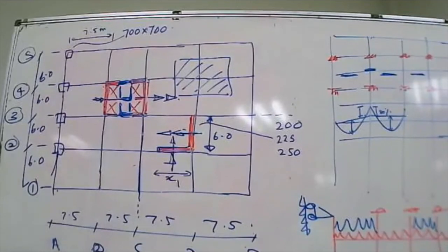Is that clear? What you do is important when you are curtailing the bottom reinforcement. But no need to be generous when you are curtailing the top reinforcement. So basically, in the beam, I would be a little generous with the bottom reinforcement, because any failure in bottom reinforcement will end up with a crack.